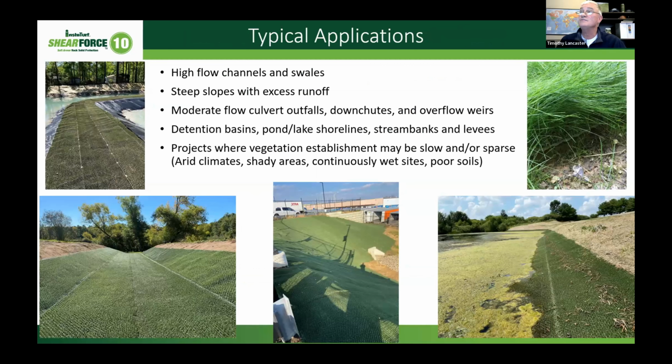Typical applications, of course, are going to be high flow channels, drainage swales, steep slopes where you do have excess runoff coming from above the slope, say a slope along a parking lot where you've got water sheeting off of a parking lot.